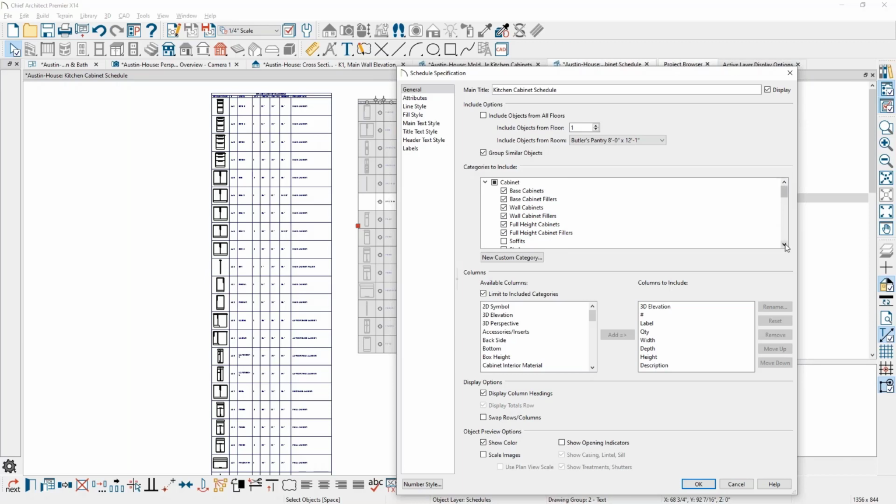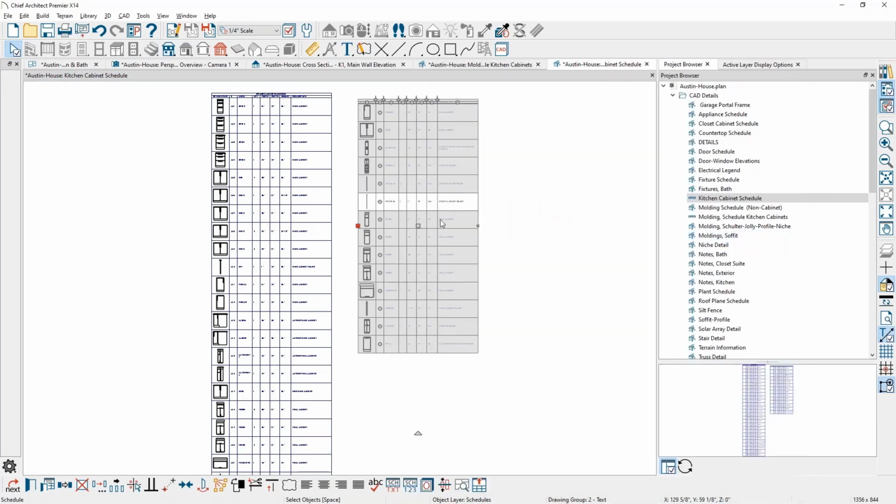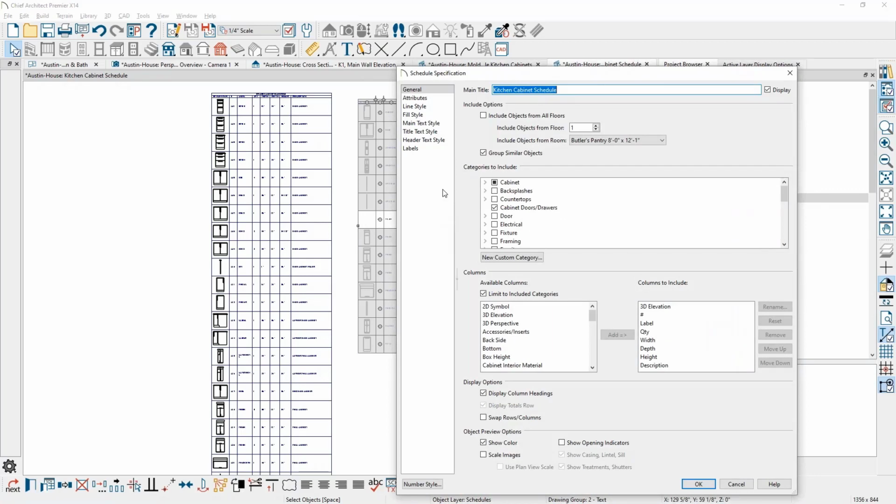Hey, Scott. If you open up a cabinet schedule, there should be a column for door handle, and I believe that's what she's looking for. Okay, so scroll down in here, and we're looking for door handle. So let's add that. And also drawer handle. Let's add that. Okay. So then let's take a peek. Wait, I could then remove the other items, right?